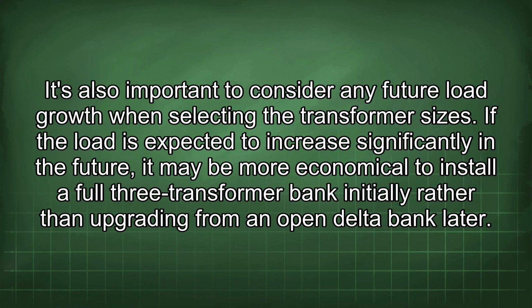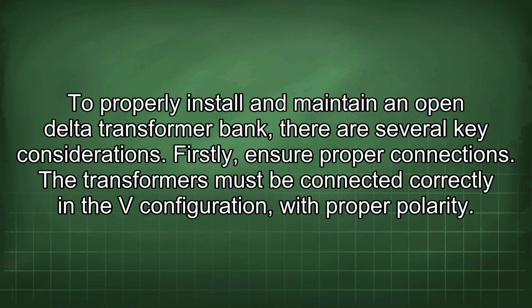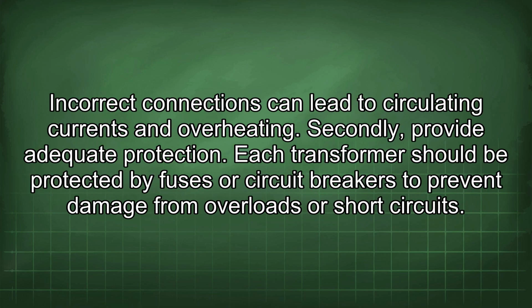If the load is expected to increase significantly in the future, it may be more economical to install a full 3-transformer bank initially rather than upgrading from an open delta bank later. To properly install and maintain an open delta transformer bank, there are several key considerations. Firstly, ensure proper connections. The transformers must be connected correctly in the V configuration with proper polarity. Incorrect connections can lead to circulating currents and overheating.